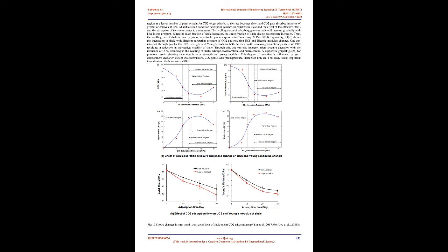The core sample was inserted into a sample cell for the application of confining pressure. Then, the volume calibration tests are undertaken to get the reference chamber volume and void volume. The system was vacuumed and then supplied with methane gas at equilibrium temperature and pressure. The pressure response with time was measured while opening the valve to release the methane.